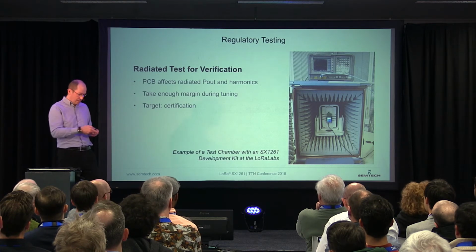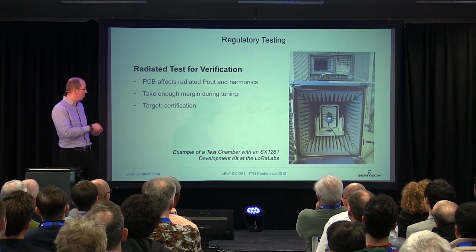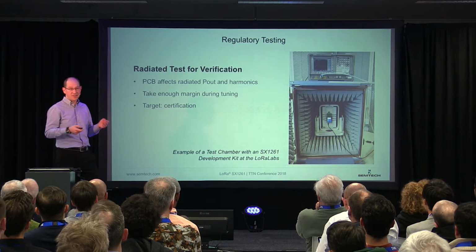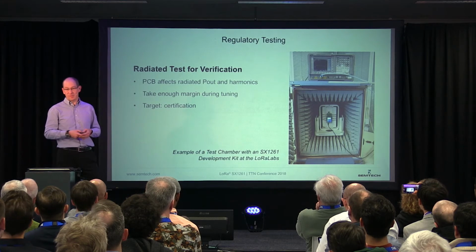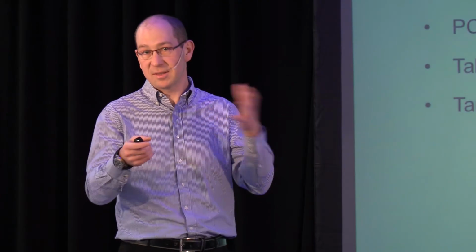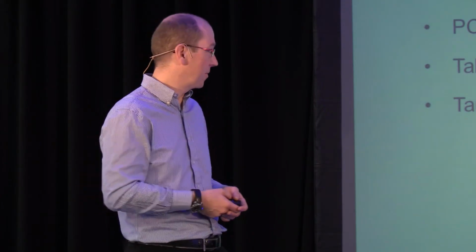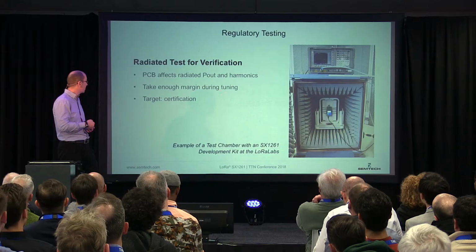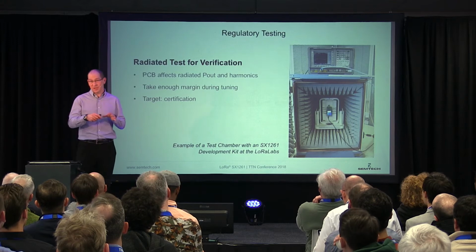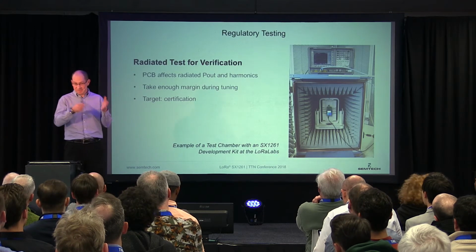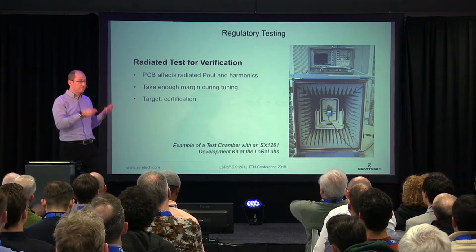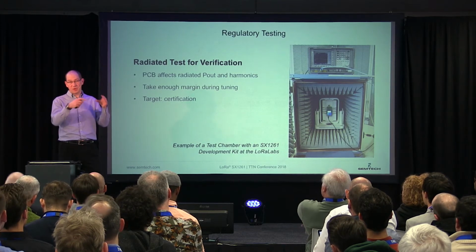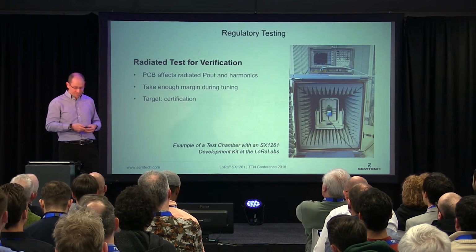So here I've used this kind of small chamber, but you can also do it outside in free space. It's more or less the same behavior. But one important thing is that you have to take some margin for the harmonics especially, because most of the time, when you use the antenna and you implement the battery and the housing, you will have degraded performance.